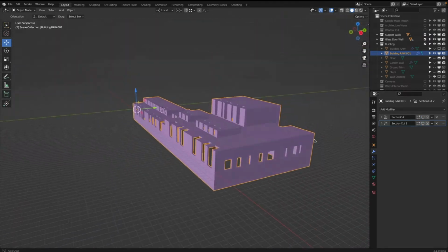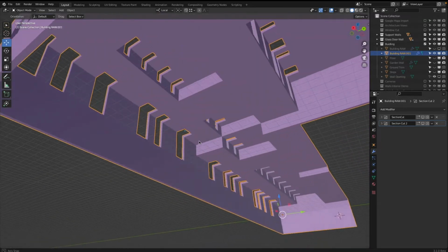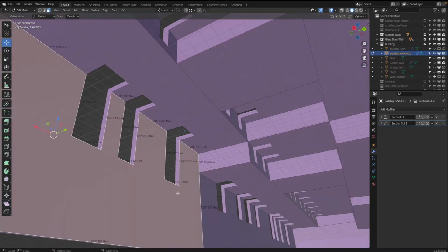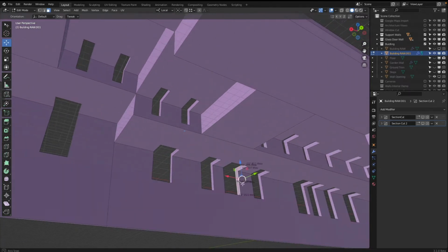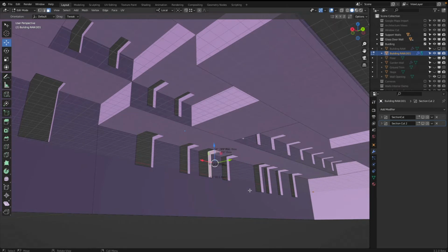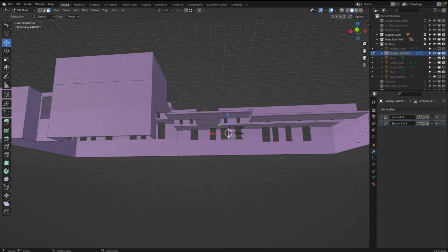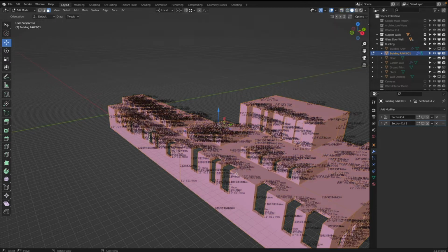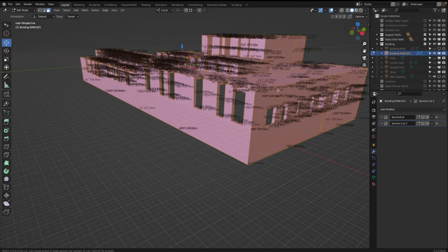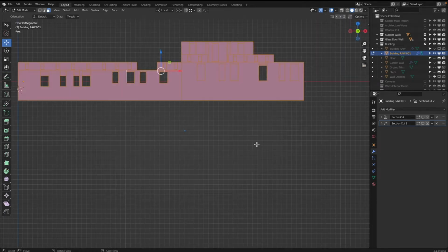Okay, so now because I applied all the other modifiers you had in your list, minus these two, if I go into edit mode, look at that. Now I have actual geometry I can touch, no? So I think this makes it very, very clear. So I would like from here to have one line go through. So how do we do this? Ideally, this is with the Control R, and that's not going to really work. That's the reason why we, at this point, then will use the knife tool.